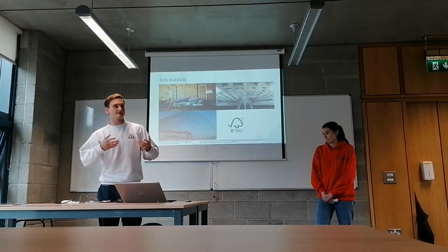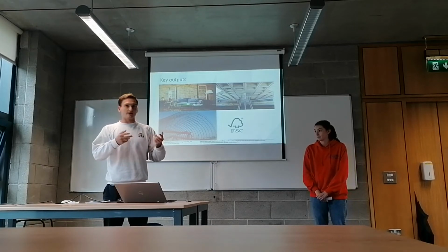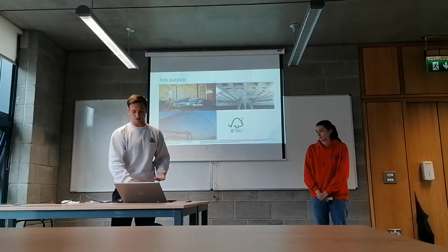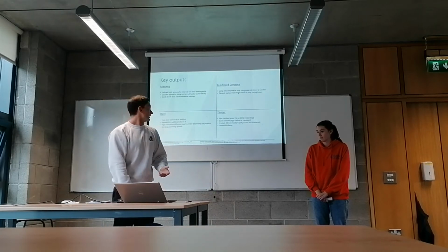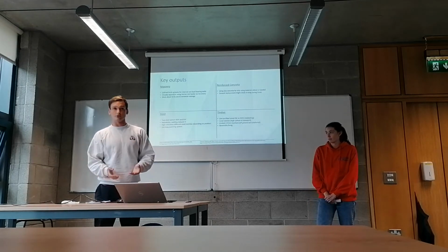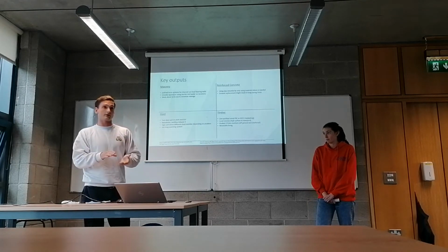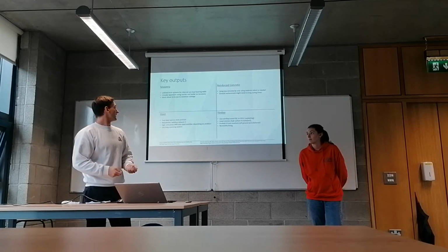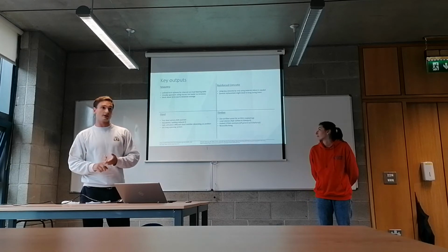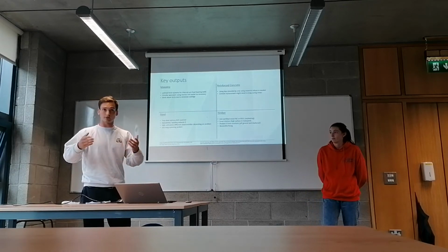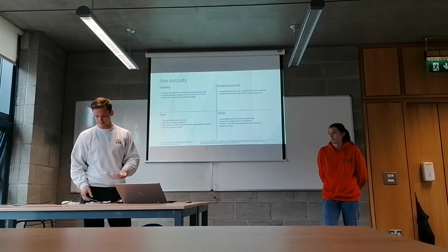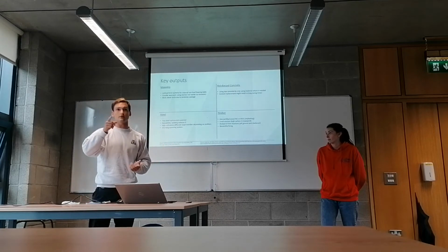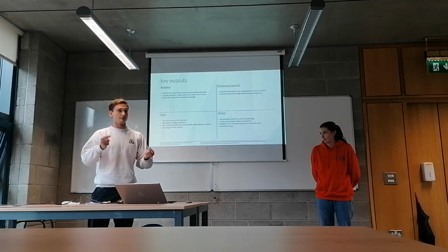And then this article gave some hints on how to use which material so it's used as efficiently as possible. So for masonry, you want to reuse the bricks later on, so you might use a mortar which is not as hard, so you can clean the bricks later and reuse them. For reinforced concrete, there's cement replacement, so you put less cement in. That helps with the emissions. For steel, there's different steel options. We heard about that before in the other presentation.